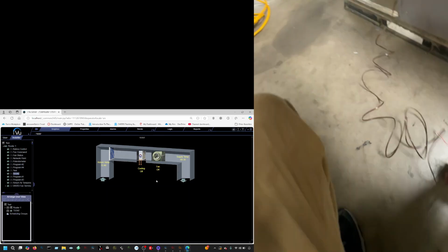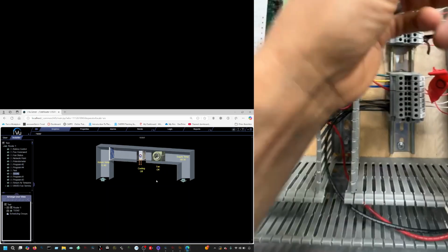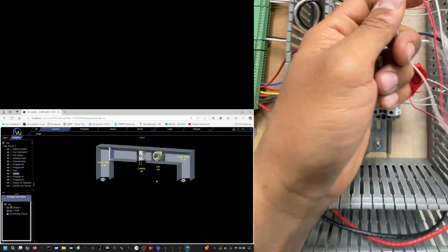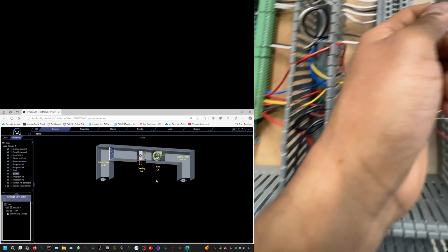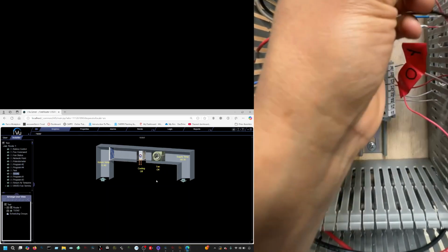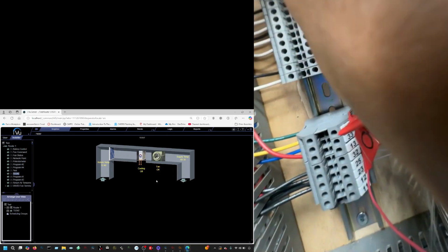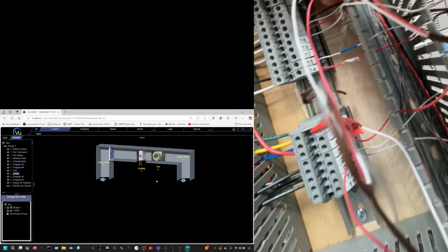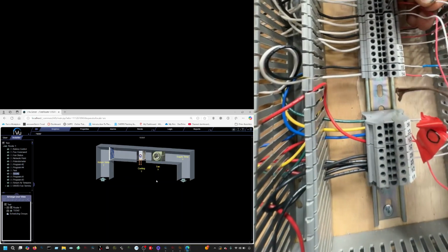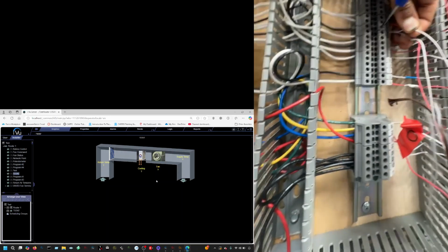So, okay, so this is the supply. Same concept. So let's bring the wire here. And you could actually do this. The ground, which I'm going to use, that's the white one. I'm going to go ahead and put it on the same one where I put the ground for the return. That's okay. They can share the ground, the common. So I'm going to go ahead and put that in there. And they're both going to be in the same hole. Okay. All right.